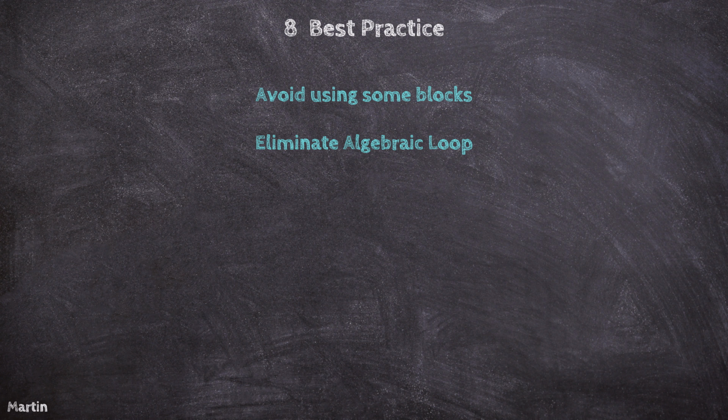In this session, we will focus on two of them: avoiding the use of certain Simulink blocks that can slow down simulations, and eliminating algebraic loops, which can adversely affect both speed and stability.